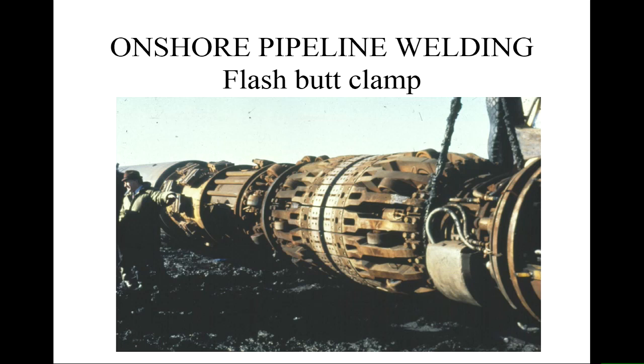So you have a special clamp for doing this, and these are the important pieces in here. These are insulators, so that you can electrically insulate one pipe from another, and therefore when you connect them up to the power supplies, you can then have a voltage put across that gap, which will drive the arc formation. It's a much bigger pipe, much bigger clamp. There's a lot of equipment inside the clamp to make sure everything's lined up, and for electrical safety you have to have quite a lot more instrumentation on these systems.